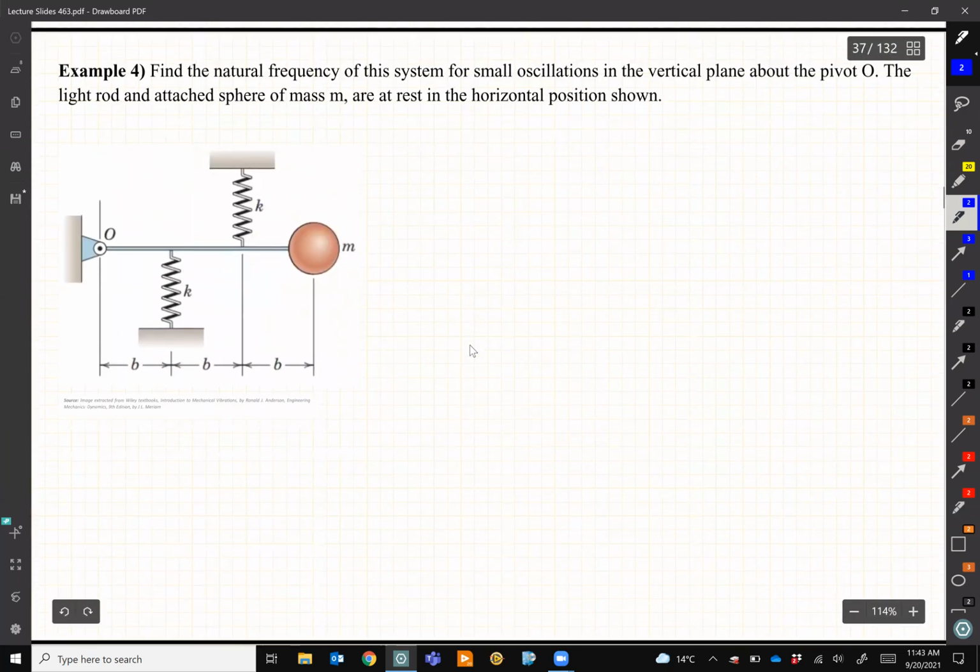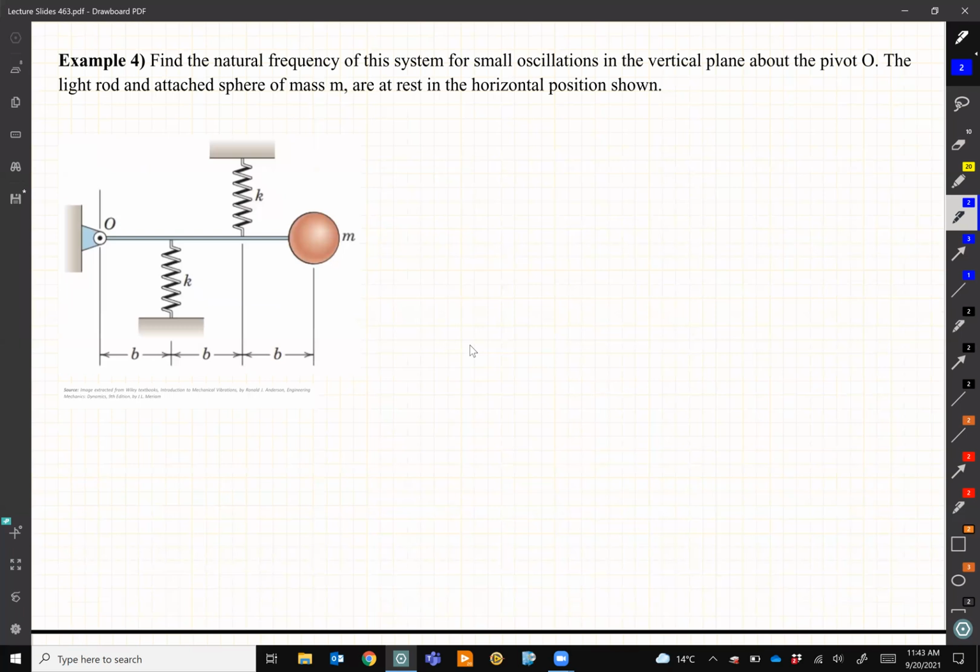Okay, so let's solve one example which is different than the pendulum, and let's use Euler's law for this one. Again, spend a minute, try to think about it. Three simple steps. First, how this thing is going to move, the kinematics, then the free body diagram, and then simply the equation of motion. And as the system said, hopefully somewhere, this is an equilibrium. So usually what you see here is the equilibrium condition.